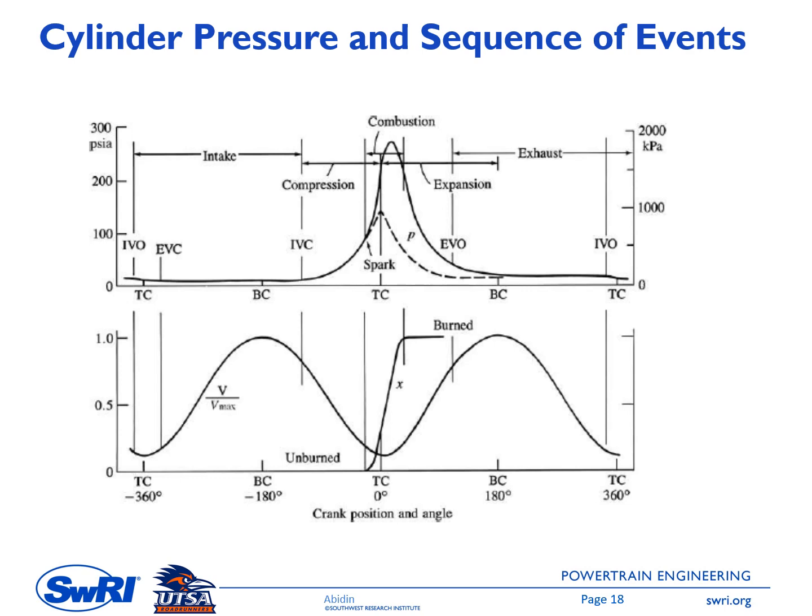And then you can see in here the exhaust valve is still open, because the exhaust valve closes at this time, and this is called the valve overlap duration. So the intake valve is already open, but the exhaust valve is also still open. Depending on the characteristic of the chamber, there might be some short-cut flow.